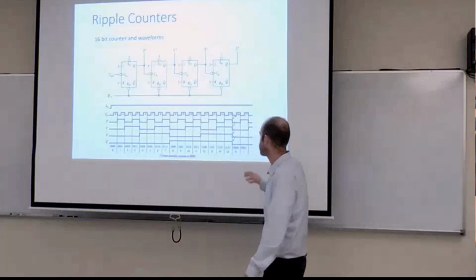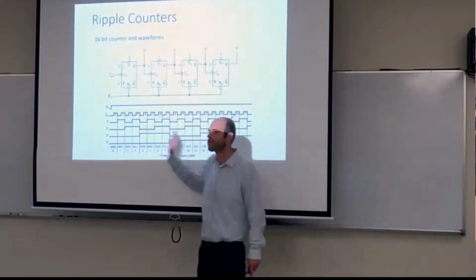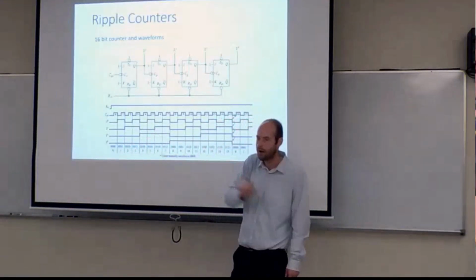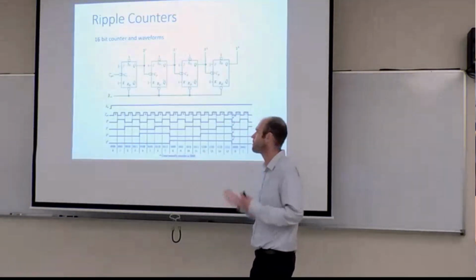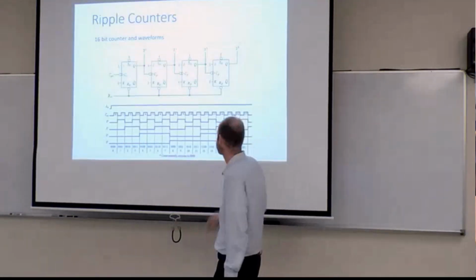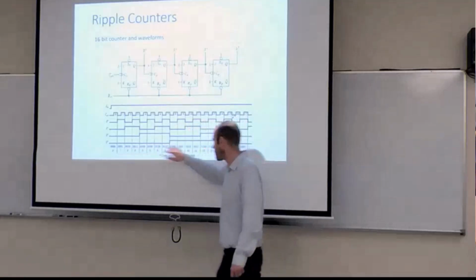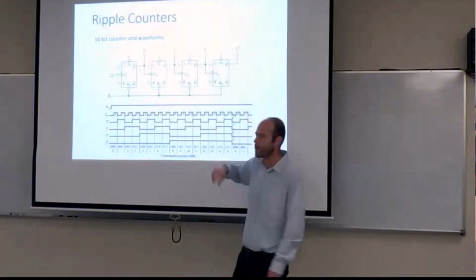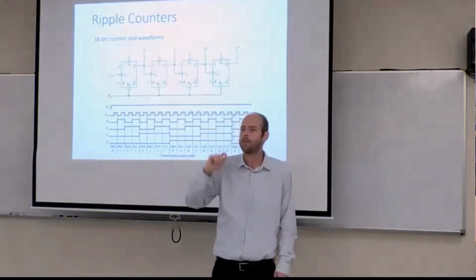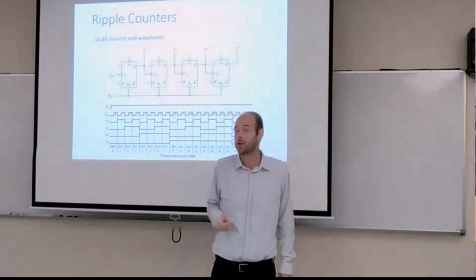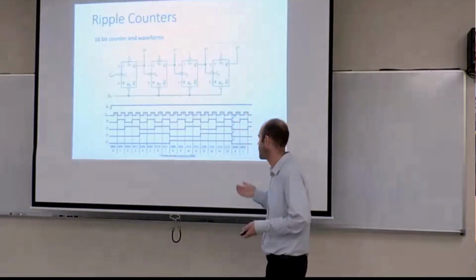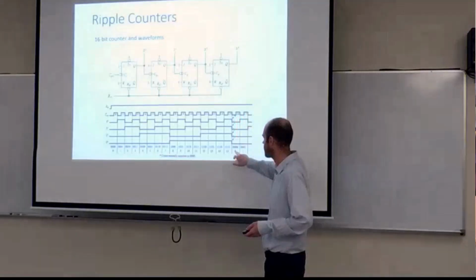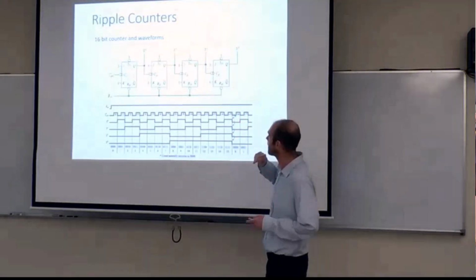So this is not like running a loop in software. This is more like setting up dominoes in a row and knocking them down. They only have one way they can fall because of how they physically exist. So there's a 4-bit counter, counts from 0 to 15. What would be the modulus of a 4-bit counter? 16, yes, we have 16 total states, 0 to 15, and then it resets back to 0, 0, 0, 0.